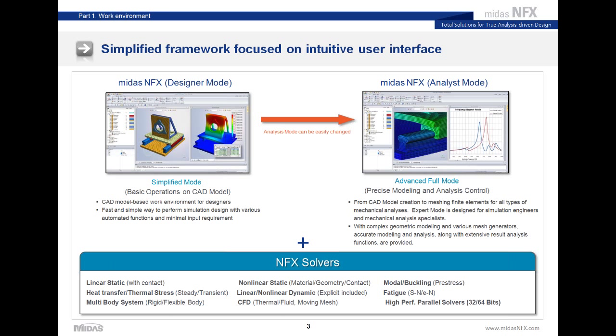The interface is composed of two modes. So you have the designer mode and the analyst mode. First, designer mode is more simple and provides an efficient way to import a CAD model and to perform all kinds of simulation design with various automated functions and minimal input requirements. After that, the analyst mode provides the tools you need to create complex CAD models directly into Midas NFX, and you have also more meshing and analysis functions. And in the two modes, you can use all the solvers of Midas NFX, the linear, nonlinear, CFD, etc.